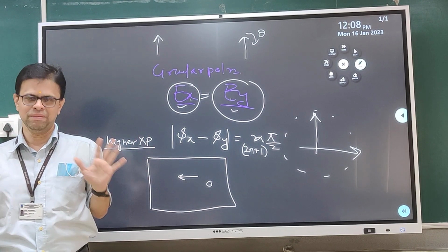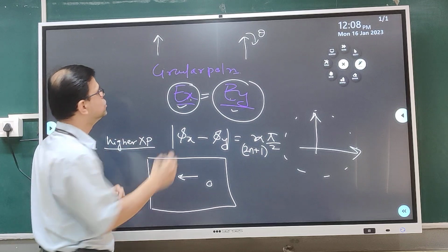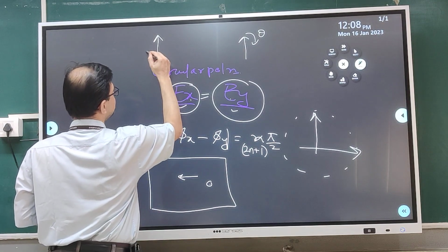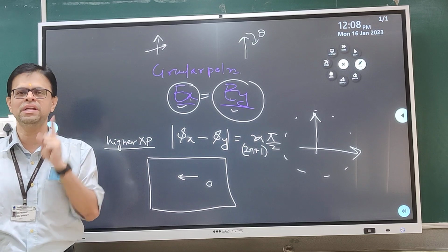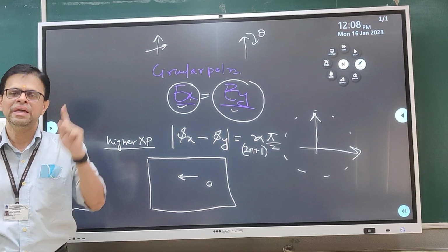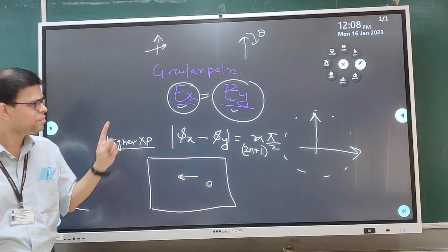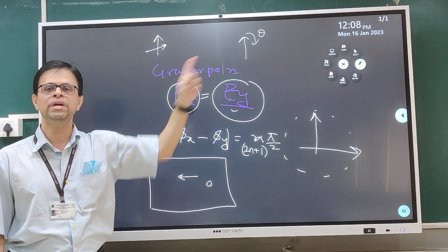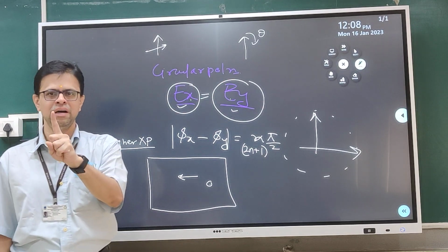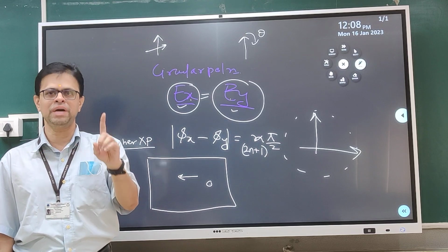so that I will measure the copolar measurement in the E plane. After that, suppose I keep this transmitter antenna orthogonal. In this scenario, what is the received signal at the antenna when the polarization of the antenna and the receiver are not matched?